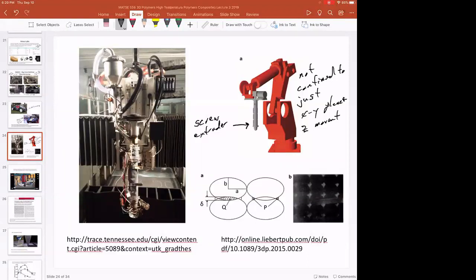One of the things that comes up when you're doing extrusion like this is that your extrusion bead or your road looks something like this right here. So this is 4 roads: 1, 2, 3, 4. And how this would be printed, it'd be printed in 1 layer here, and then 1 and 2 would be printed on top of 3 and 4. And the result is a micrograph that looks like this. So this is a bundle of roads.